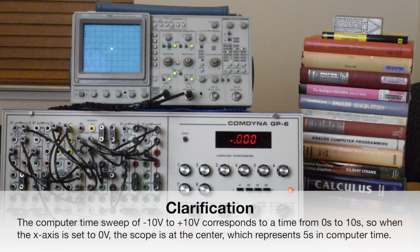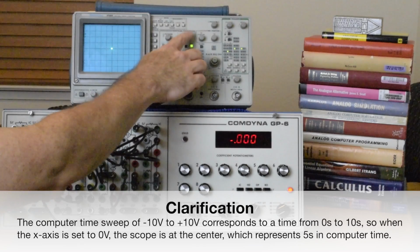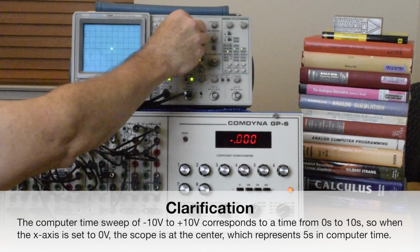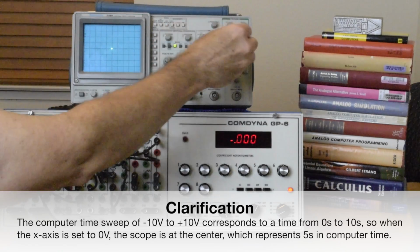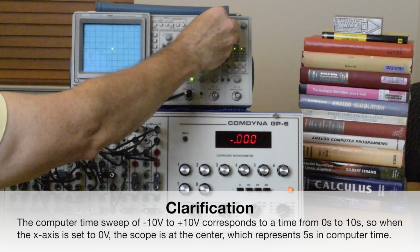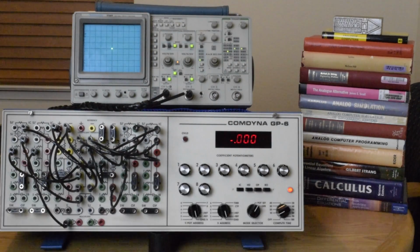The Y ground position is adjusted with the actual second channel position knob here. So I've got those adjusted fairly well, but we'll go ahead and show you that. So that's how you would adjust there and there. And I may have a little parallax error because I'm not looking directly at the screen.